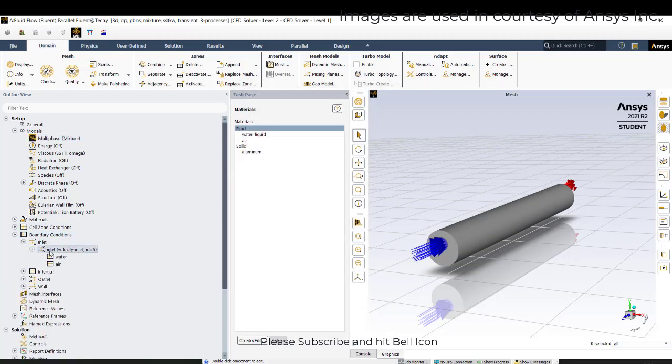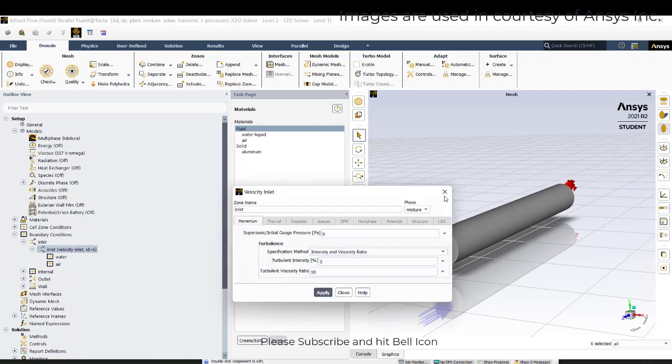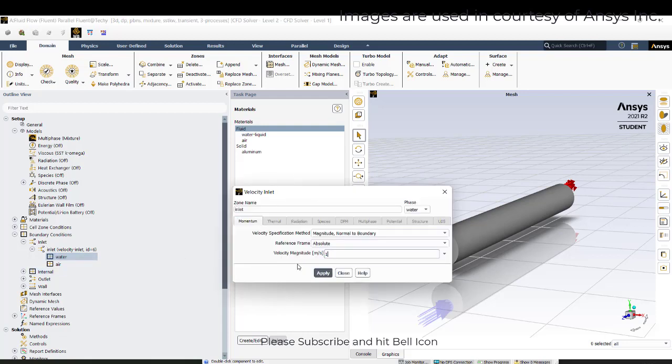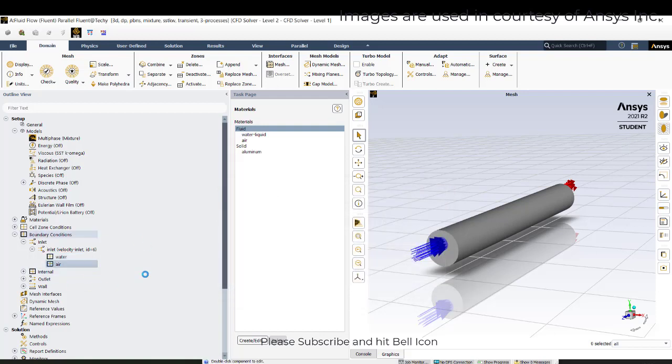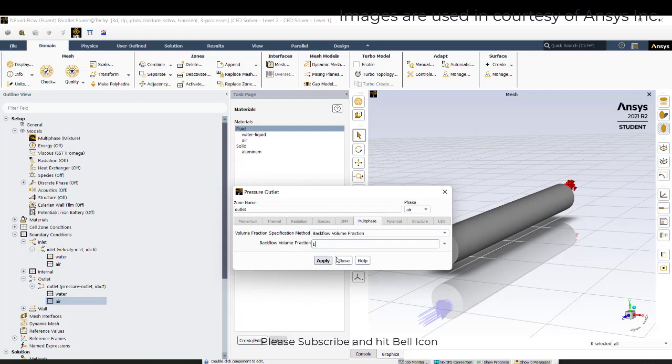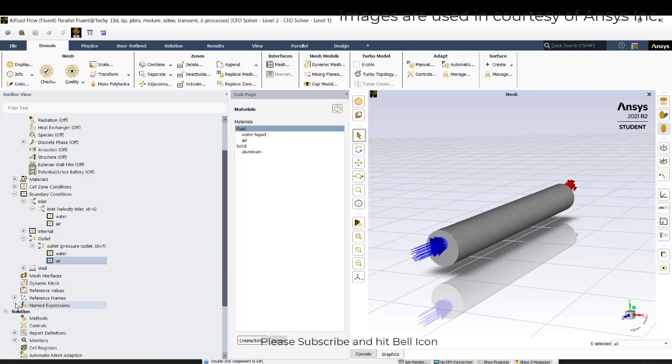Now I'll go to boundary conditions and the inlet velocity. In the inlet velocity you enter the velocity of the water only, since there is no air, I mean there is only water entering here. Maybe I'll take water as 1.5 meters per second. Apply, close, and air is 0, so no air is entering. You can check here: yes, air is 0. In the outlet condition, there is backflow for air only, no backflow for water. So we can take the backflow volume fraction of air as 1, so no water comes in when there is reversed flow at the outlet.